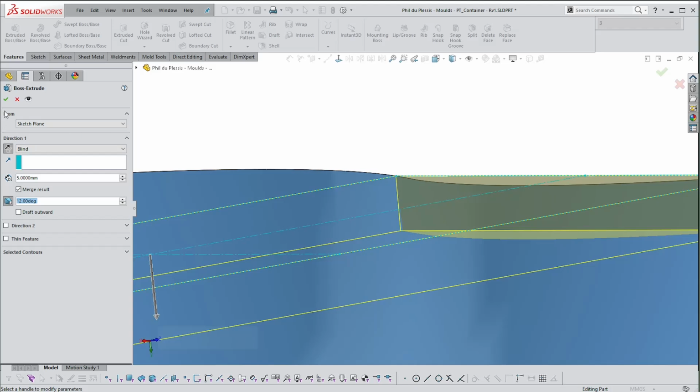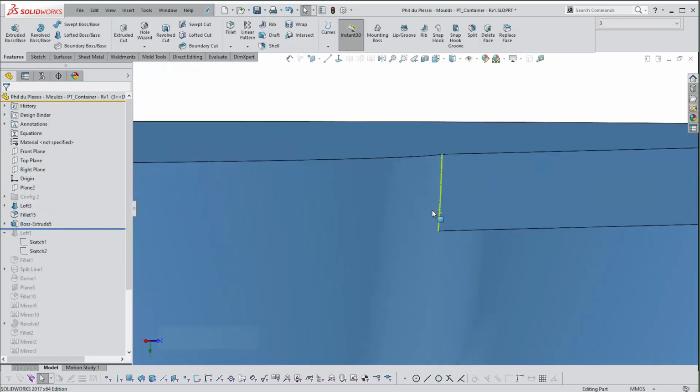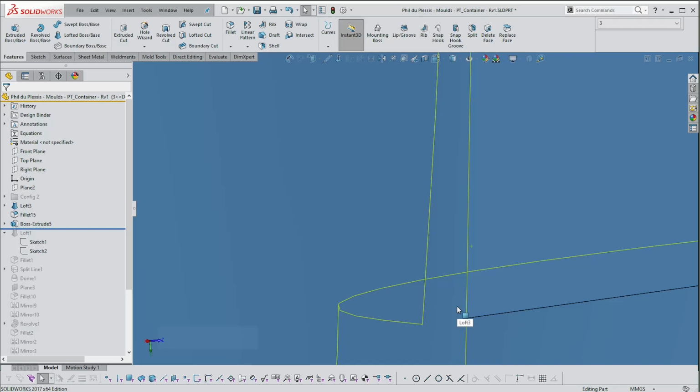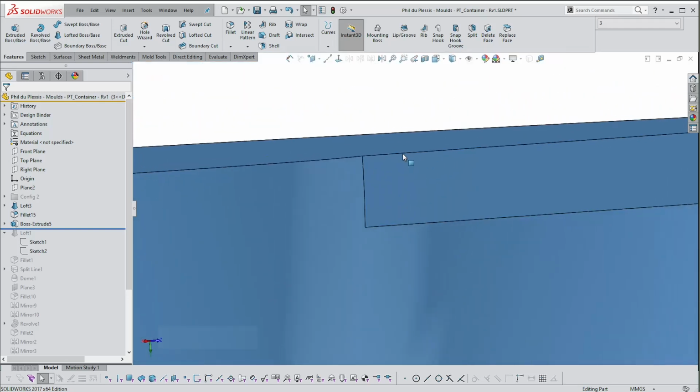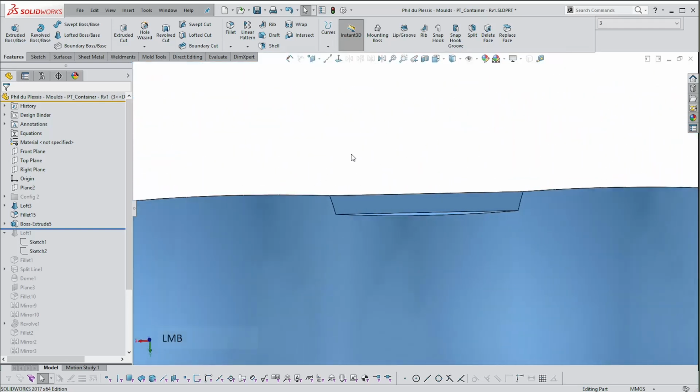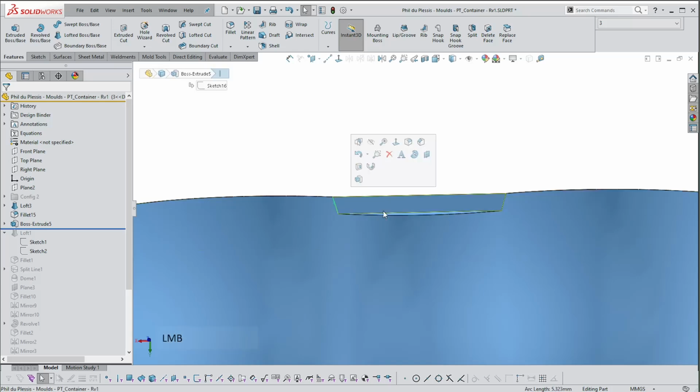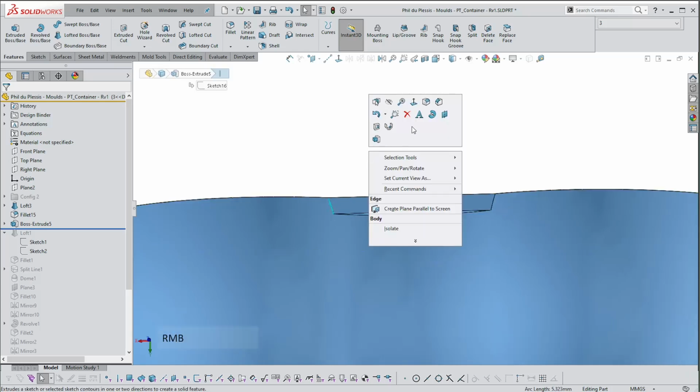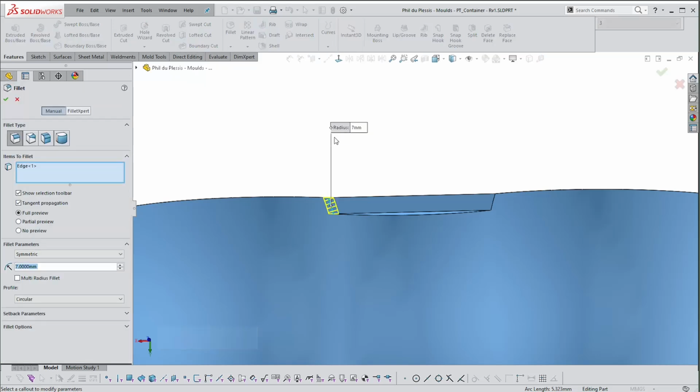Whatever you do, if you say okay, just check that you don't have 2 faces connecting with one another, because if you do, this next step won't work, which is to put a fillet in on all of those points. So I'm going to right click, fillet, and at the moment that's at 7. So I want it to be about 20, not 290, 20.